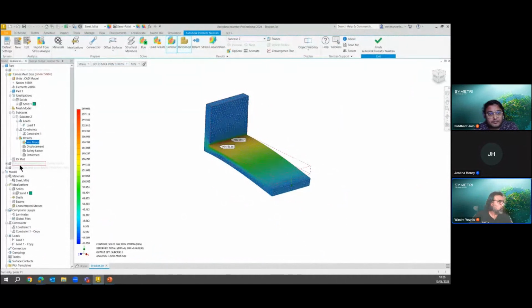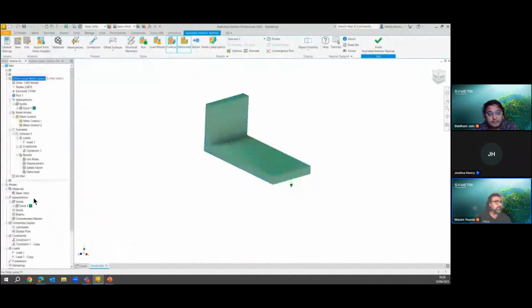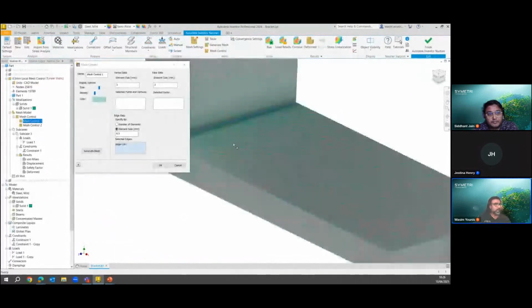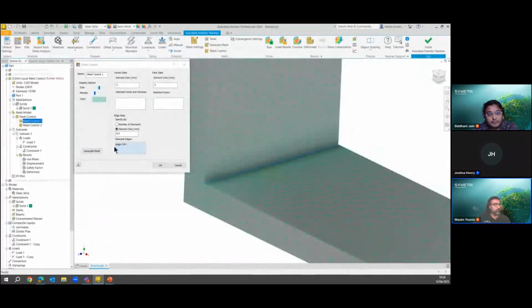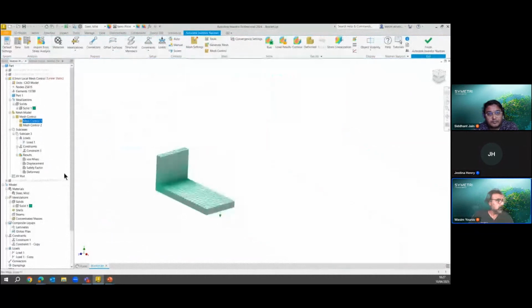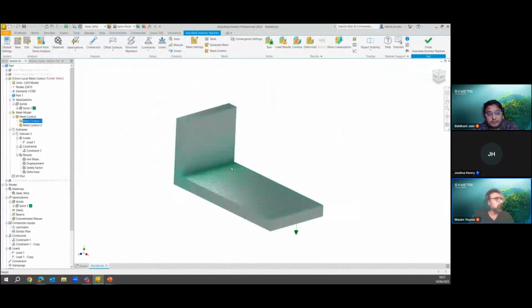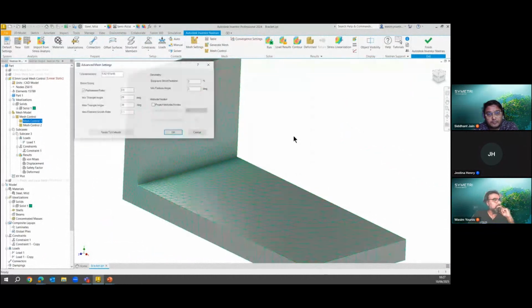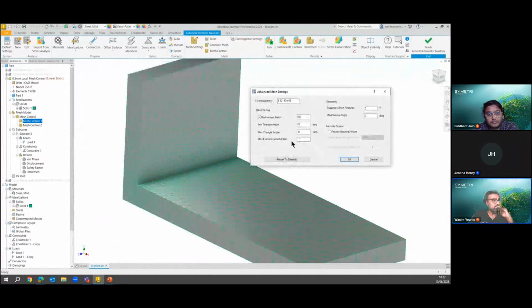With the third one, I did not change the global mesh size. I simply put a mesh control on the edge. You can see here, I put the edge along there, and I said make it half, well, less than half of 1.5. Also, just a little tip, I think everyone's familiar: when you put a local mesh control on in mesh settings, you tend to change this here.